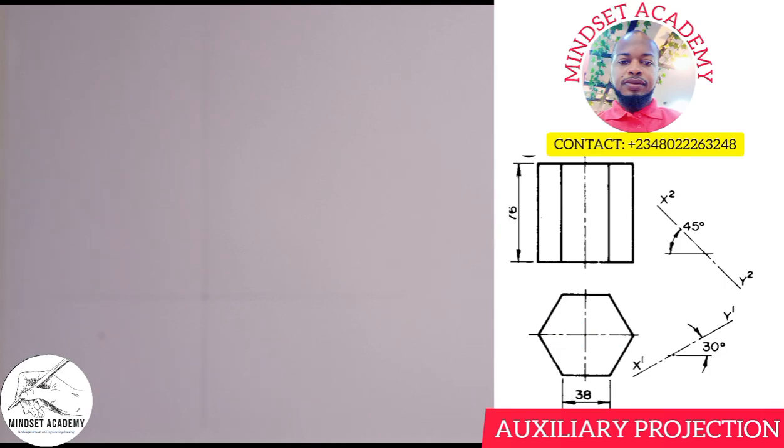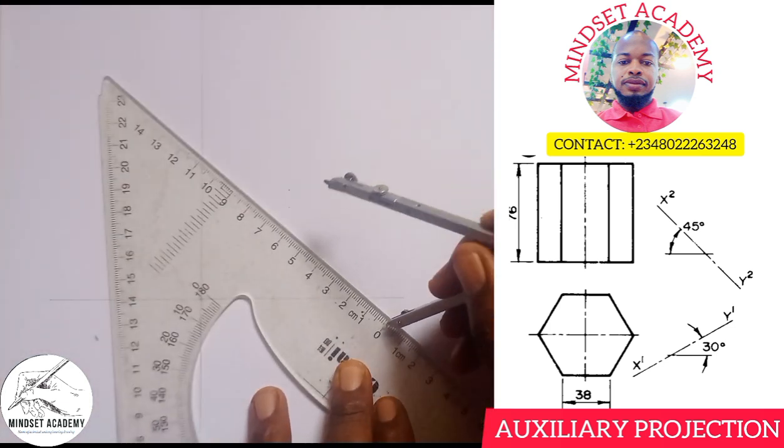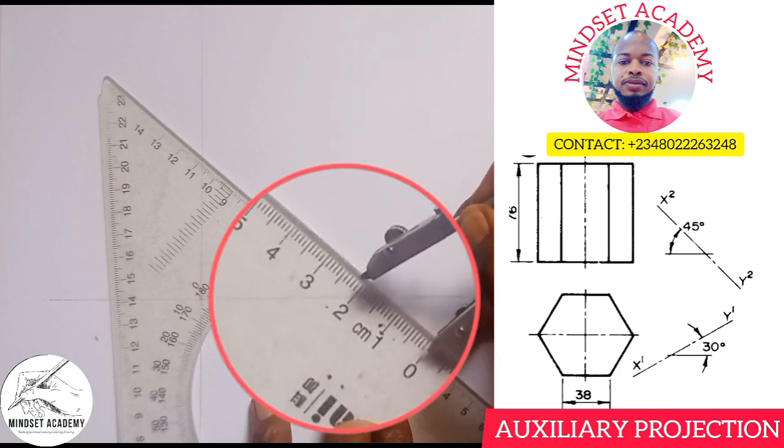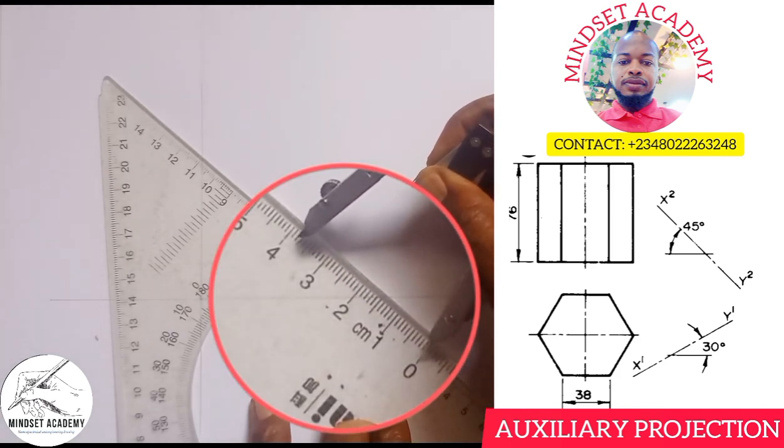I'm going to take my compass and place it. The radius given here is 38. As you can see, it is a regular hexagon, so one of the sides is 38, and we have 6 sides. That's why it is a hexagon. So I'm going to measure 6 different sides. This is from 0 to 38.